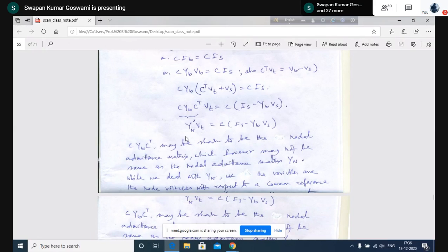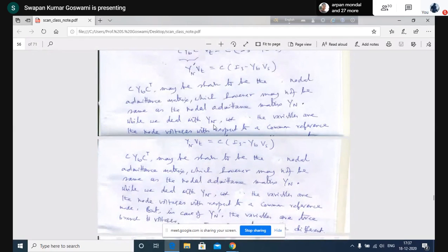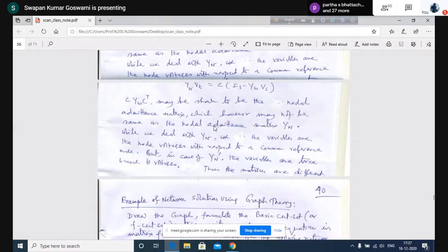Obviously now this is completely written: that equilibrium equation you have formed using the cut set matrix, that means the basic cut set to element incidence matrix. So using these A, B, and C matrices, we can write network equations. After writing the network equations, you are now in a position to solve for Vt. If you solve this equation, you will obtain Vt.